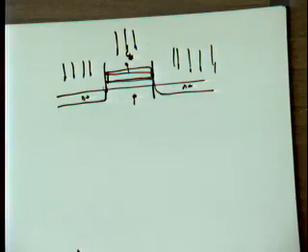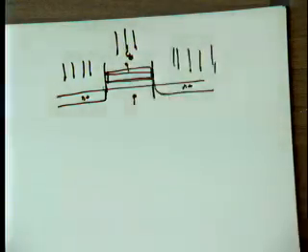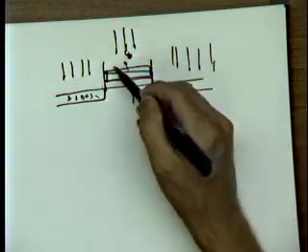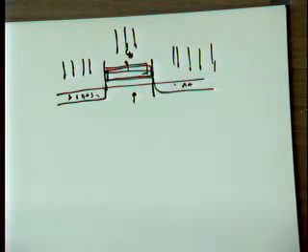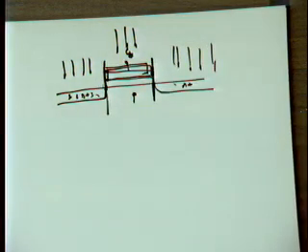So this is called self-alignment. It's a beautiful concept, right? You put the gate down over the silicon dioxide, and then you shoot all those ions at it with a huge amount of force. So they end up here, and you have all those impurities. And the gate, we have this polysilicon. The polysilicon is just going to take those things, and they're going to go into the polysilicon. And as a result of that, you get a perfect edge between your source and your channel and your drain and your channel, ideally. But then I start cooking again.